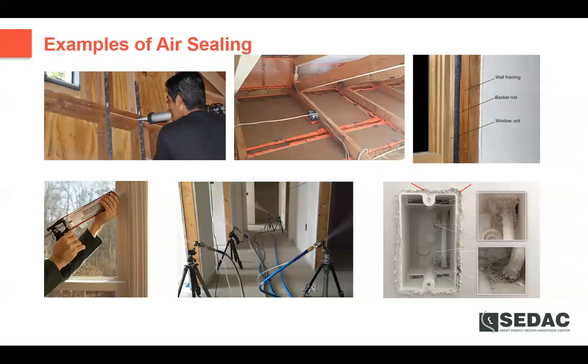We also have some pictures of a proprietary type of air sealing method. It's not that we're proponents of this, but it's a very interesting method where, before the house is occupied, before you have a lot of stuff inside there, it's called AeroBarrier, where you pressurize the house with a blower door, and these misters are spaced around the house, and that particulate matter that is blown into the air finds every small leak where air is leaking out of your building, and does a very effective job at sealing.